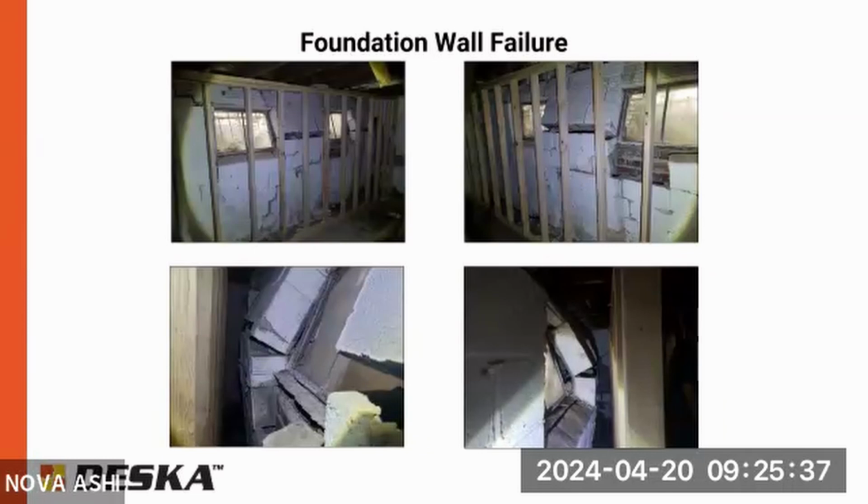Here's another example of a wall that just bowed in too far, it needs to be replaced. It should really have lateral bracing, temporary lateral bracing there as well. But in this case, the owner just had a contractor come in and put vertical bracing until it could be replaced.